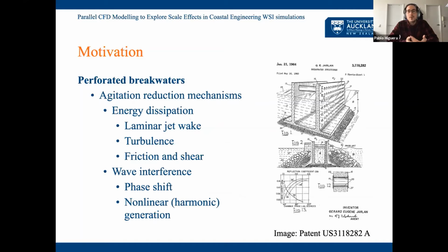So how do they work? Well, they work to reduce agitation by two means. First one is by dissipating energy. So energy gets through this porous medium and you have some laminar flow. If you have higher waves, you get into the turbulent regime, and obviously water experiences friction and shear, and that reduces the amount of energy.